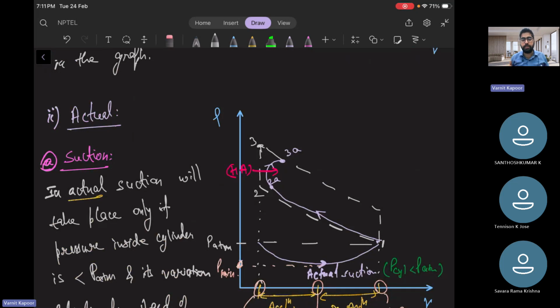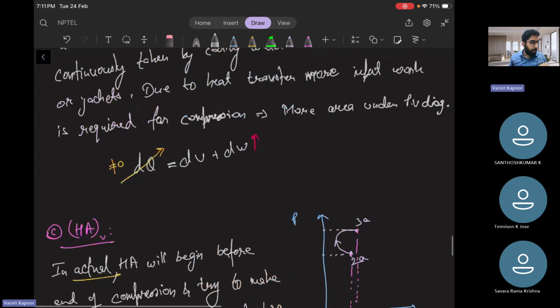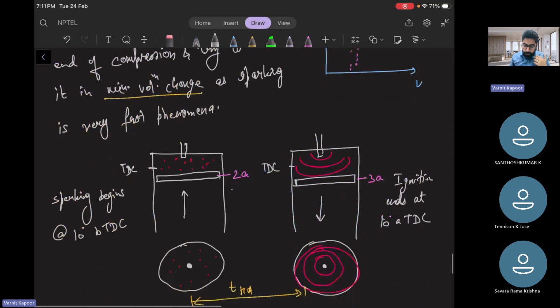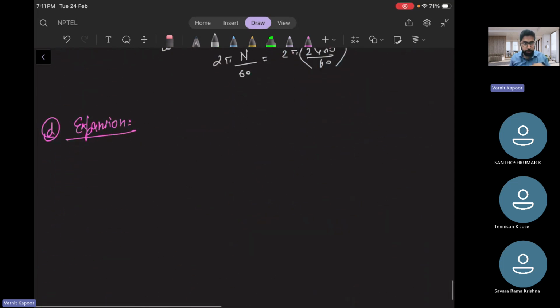Whereas expansion is a process where work is produced. The power stroke produces the work basically. So during the compression, the water jackets were rejecting heat from the system. For that, we need to give an extra amount of work to the system, to the cycle.